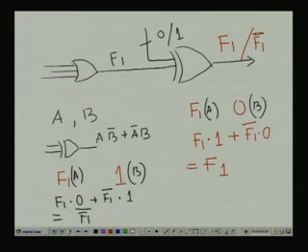So, in this way I can get a complement of the output function. This is another programmability we have added here, just by feeding a 0 or 1. So, this can be a control line. If it is 0, as it is I will be getting the function that I want, the output of the OR gate, and if I want the complement, then my control line is 1, then I will be getting a complement of the output.